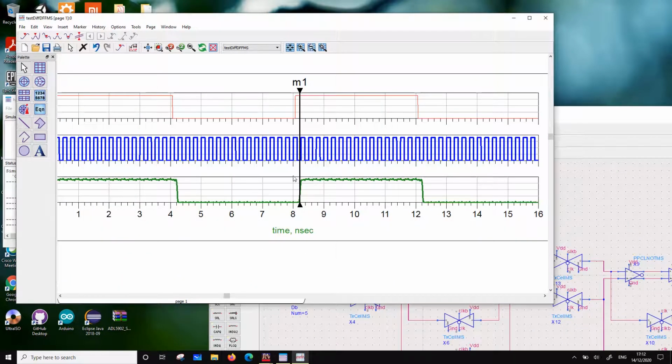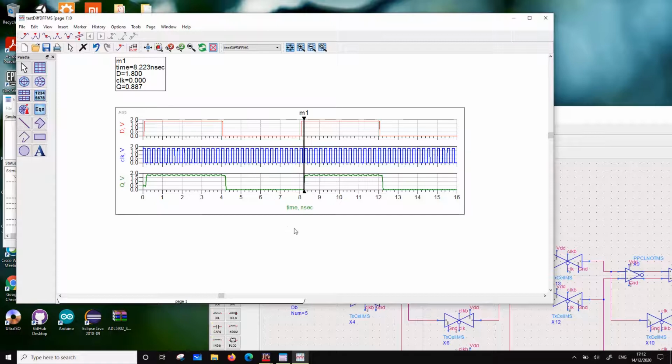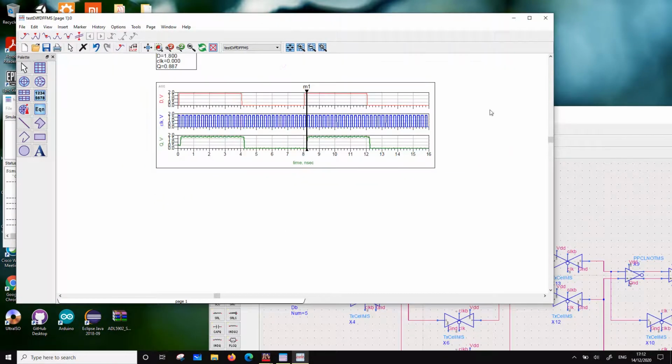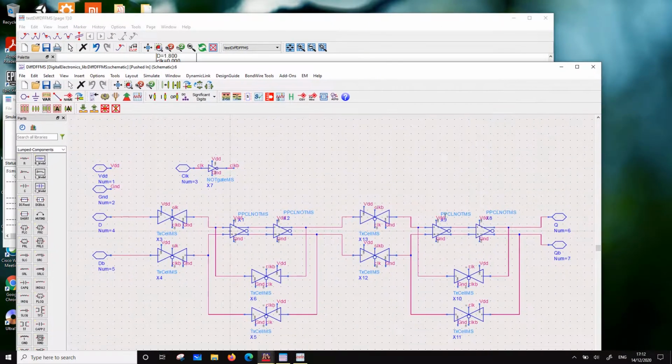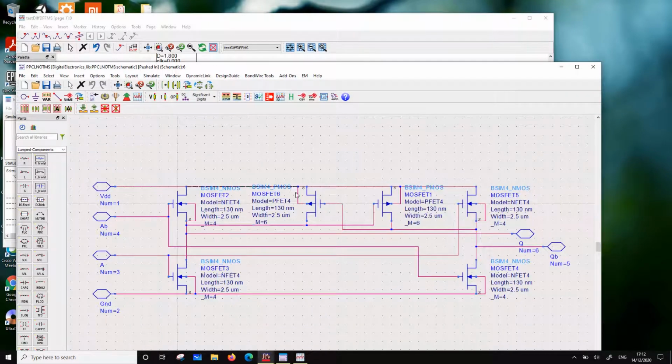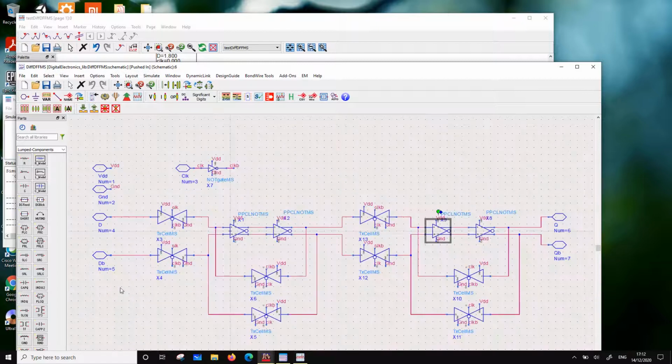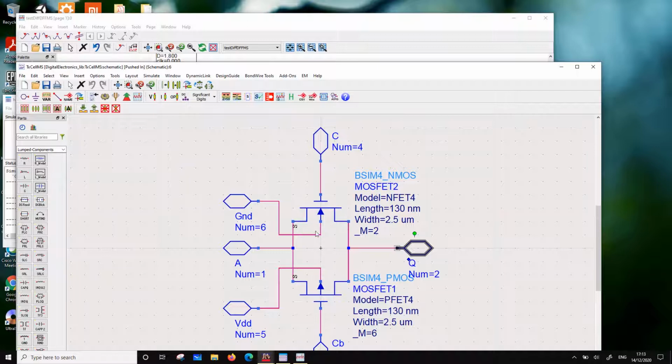So that is violated, so you cannot operate the system at that 4 gigahertz. Okay, can I speed this process? Yeah. What is slowing down your process? These positive feedback can be made faster, or the output capacitance can be reduced somehow, right? Another thing is that you can make this a large device, but then you have to drive higher capacitance, higher resistances, right? So RC delay is going to improve, but capacitance is going to add up, right? So all these things you have to keep in mind.